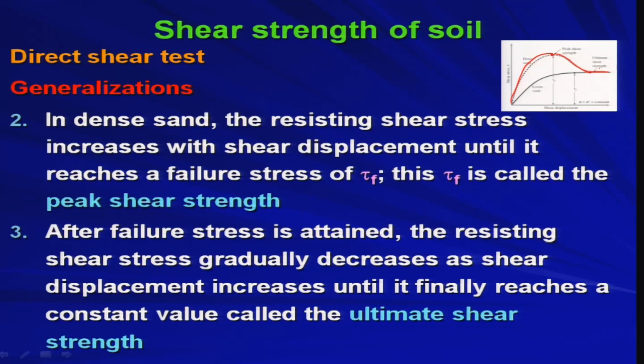So you get two regions for the dense sand. One is the peak shear strength, which happens at the failure, and the other is the ultimate shear strength, which happens at a large amount of shear displacement.